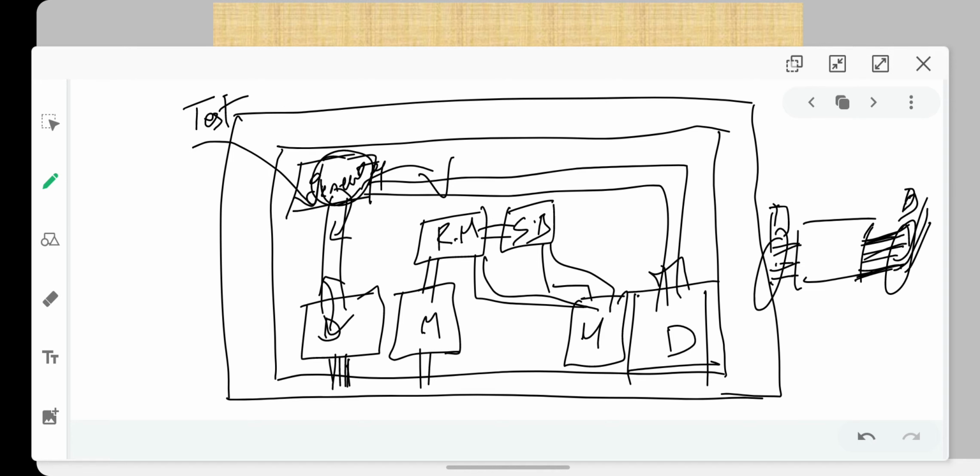From the write side, whatever data you require to drive into the DUT, your generator is going to put the data into your mailbox, and from the mailbox your driver is going to take the data and put it onto the interface that is connected with the DUT, which is called the virtual interface. This virtual interface is also another concept we will be discussing in future sessions. When your driver takes the data and puts it onto the interface, the data is driven to the DUT.